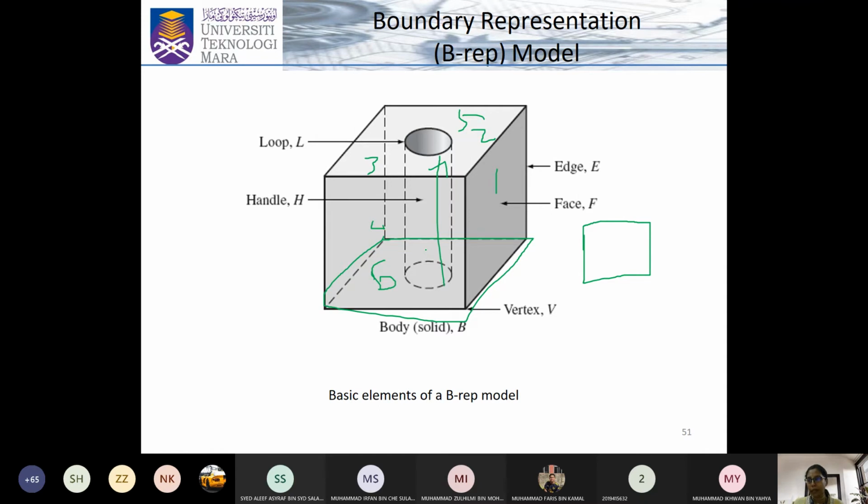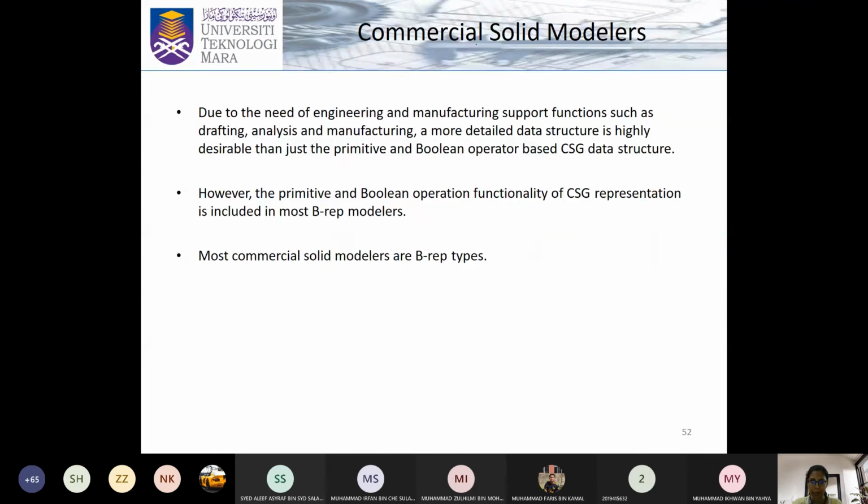And then if you want a sphere, for instance, what do you need? You need the major axis, one radius this way, another radius in the other direction, and its revolution, then you may get a sphere. So these kinds of things are possible as soon as you actually draw quick models. That means it's being done by the Boolean concept. But before the Boolean concept is made, every shape is actually formed through a boundary representation. So basically boundary representation means you're building your 3D model based on boundaries. Okay, so that's the idea.